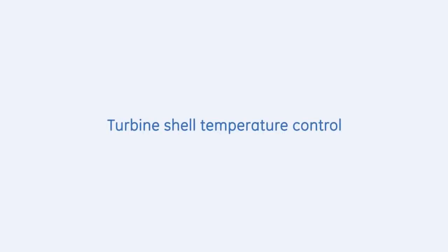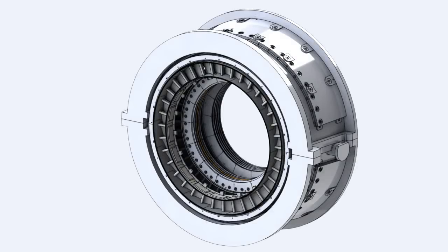For efficient gas turbine operation, clearances between all rotating and stator parts should be as tight as possible. As the turbine shell controls the radial and axial position of all turbine stator parts, the shell should be isolated from the high temperature of the enclosed hot gases. This will ensure the control of the shell diameter and roundness to be maintained.